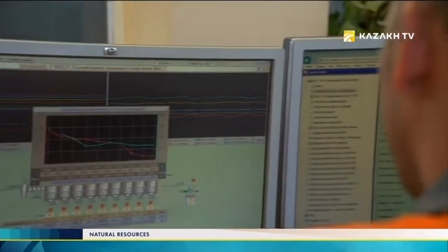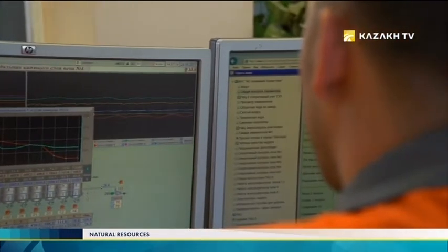We receive aluminum hydroxide to our unit. We extract water and harmful admixtures from hydrate and output final product, which is alumina. The hydrate is firstly placed into reservoirs and then poured to burden by means of special dosing device. Here we regulate the upload and check the temperature, as each burden should have its own regime. We keep particular temperature in order to produce high-quality alumina.